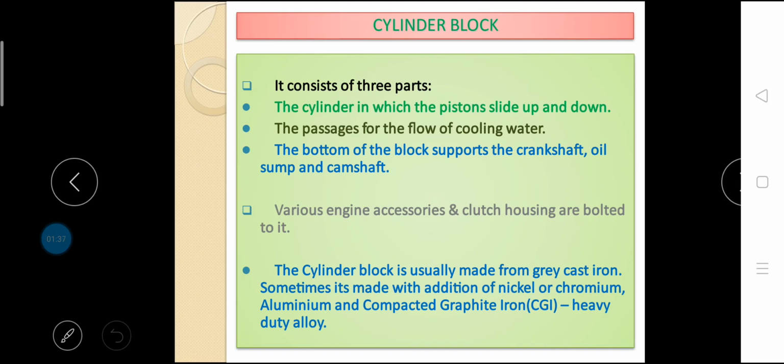At the lower end, the crankcase is cast integral with the block. The function of the crankcase is to provide support for the main journals and bearings of the crankshaft, rigidly maintaining the alignment of their axis of rotation under various engine loads. Previously, the crankcase was cast separately and attached to the block, but now the integral or monoblock construction is preferred.